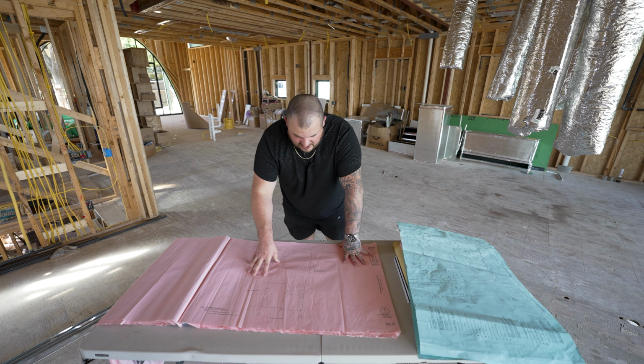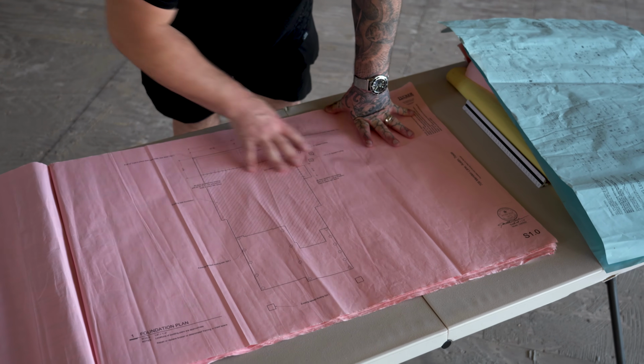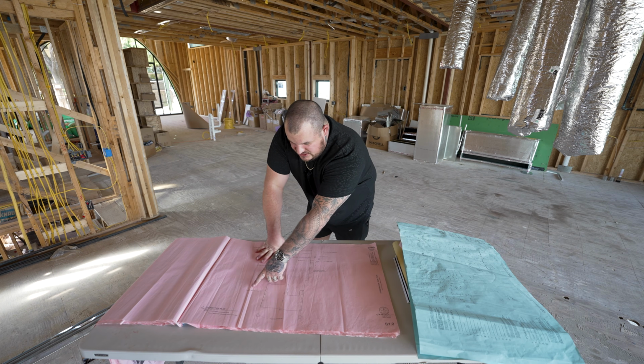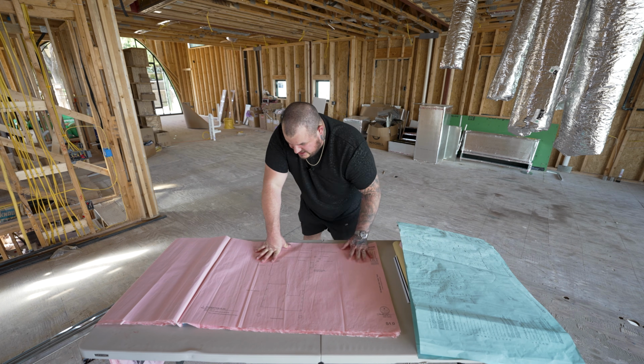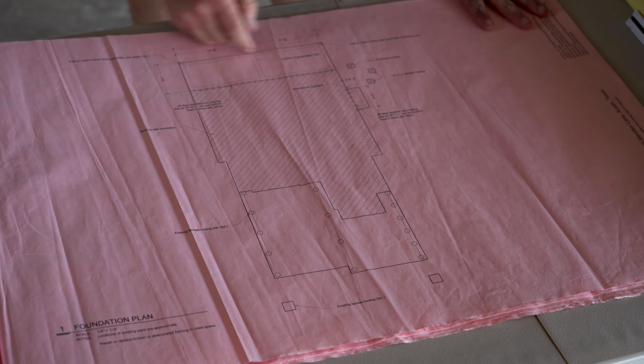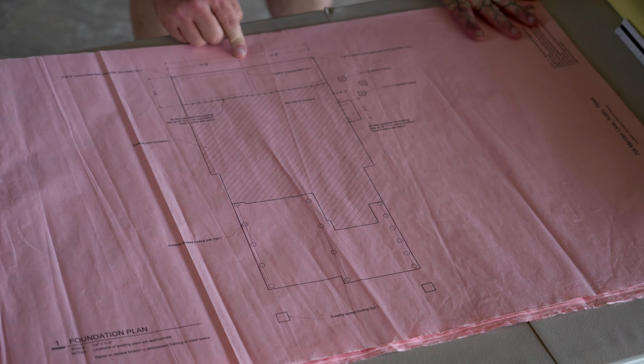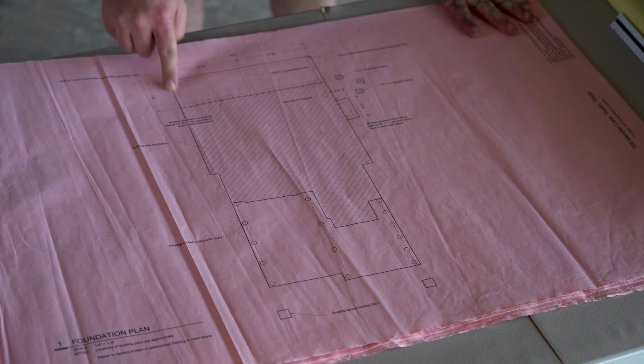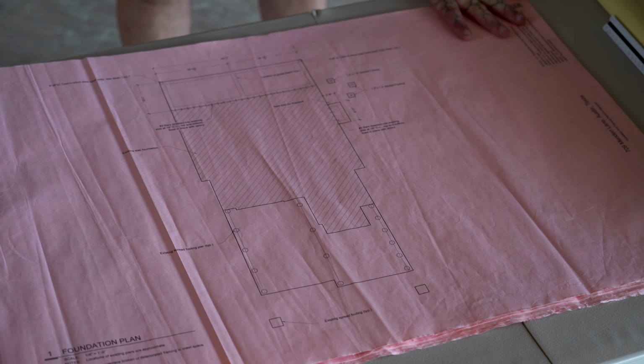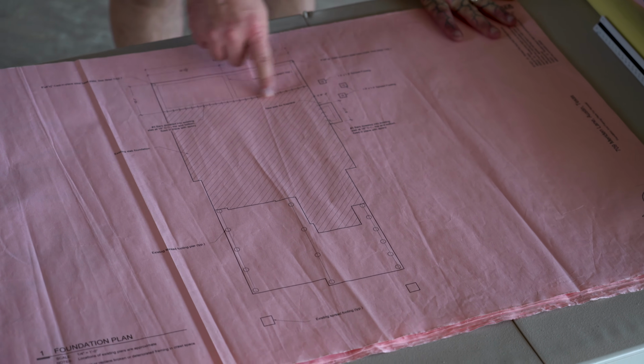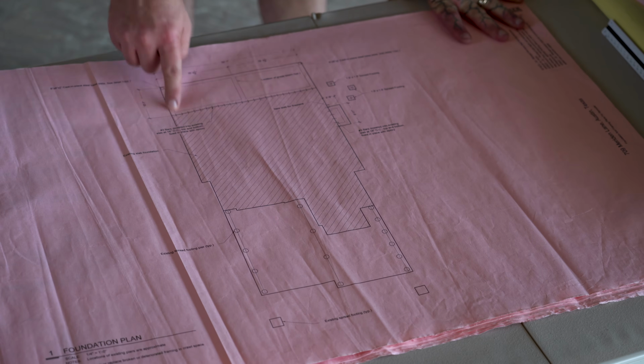You're looking at first foundation. So here's our foundation plan. This is showing existing piers, existing slab foundation. We have a new slab for our fireplace. This right here is a new piece of foundation on the back of the house. It has dotted lines. That's how you know where your grade beams are.